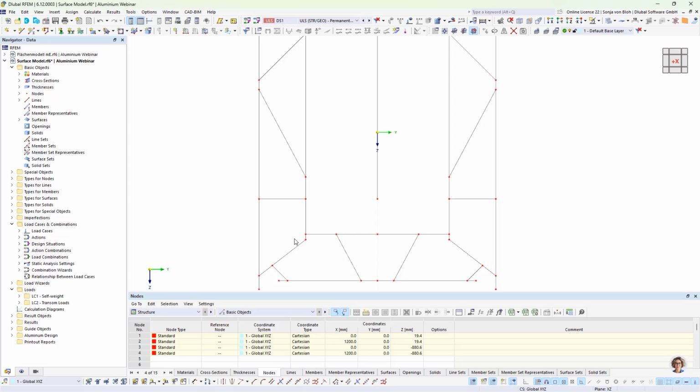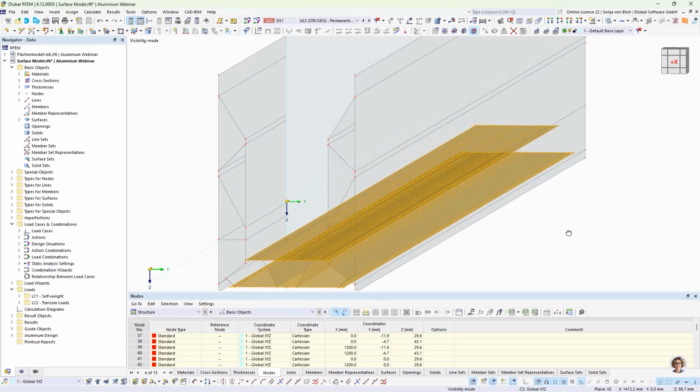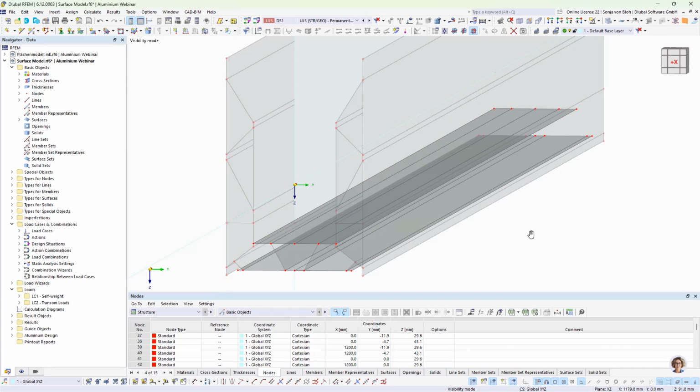In the 2 bottom surfaces that I now select, I create openings for the screws. As the openings span multiple surfaces, I merge them into single surfaces by deleting unnecessary ones and redefining the surface boundaries.